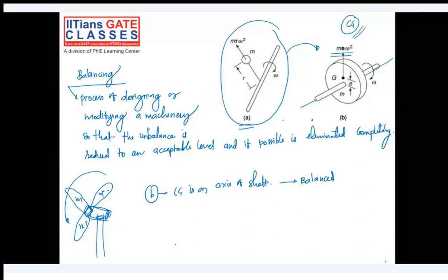Not only does it cause impact, or vibratory motion, with high noise and fatigue, it is also a human discomfort because of this noise. The machine's performance will reduce, and structural integrity and the machine foundation will also be affected. So balancing is very important in all rotary and reciprocating machines. Let's start understanding this topic in more detail. What is static balancing and what is dynamic balancing?